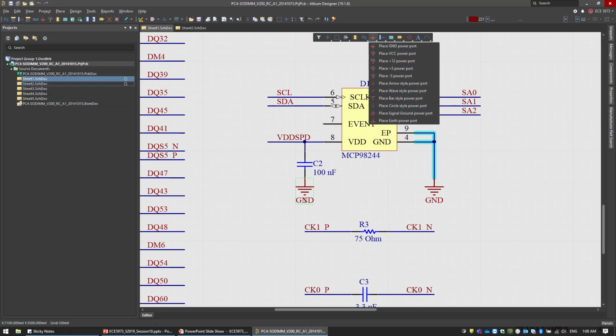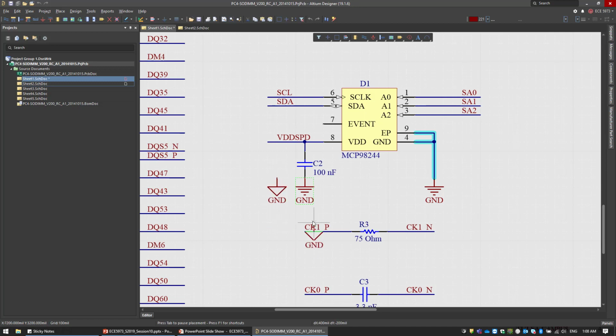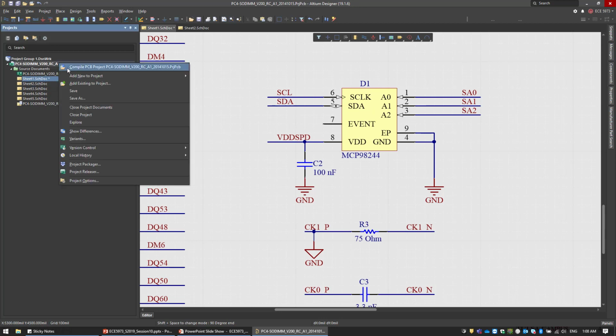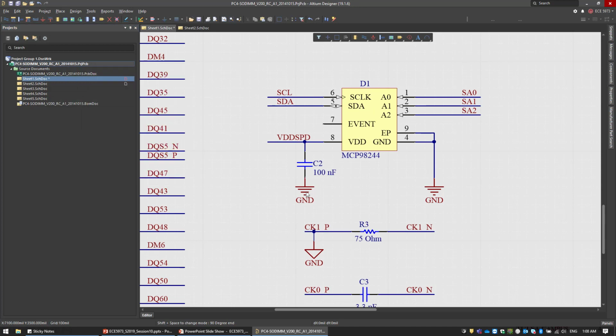Now this power board has a ground. Now if I take this one, and it has the same name, it's also ground. And these, if I connect this one for instance here, now once I combine the project in here, these two nets are connected. This one and this one, they are connected together. Basically, I'm shorting this pin to the ground because they have the same name.